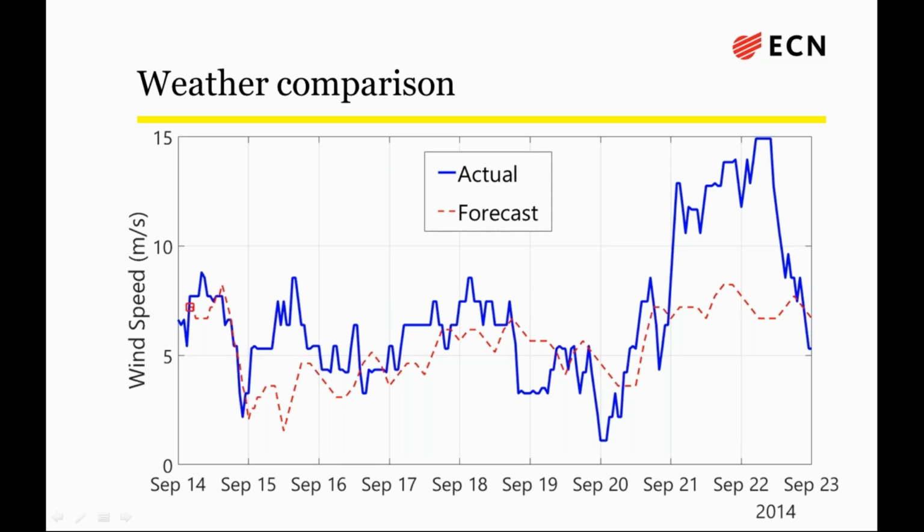And what you see is what looks like a fairly small difference in wind speed during the first day. That is causing the large change in energy loss because of the cubed effect of a power curve. What you also see is the future energy loss is much greater because in the last 2 days the forecast was very wrong. So if you have to do some work then you're losing an awful lot of energy. So that is the difference. But that's why that slide was in there. How uncertain your forecast is will entirely depend on your supplier and the location.